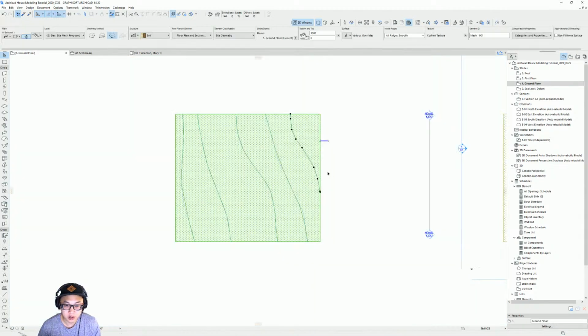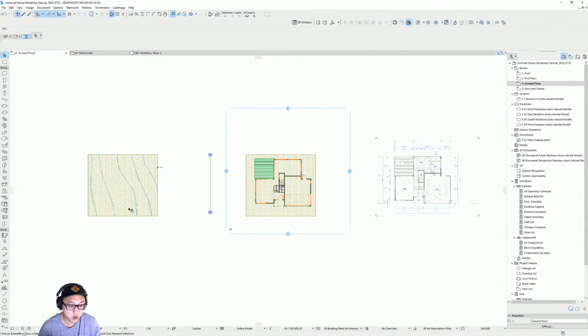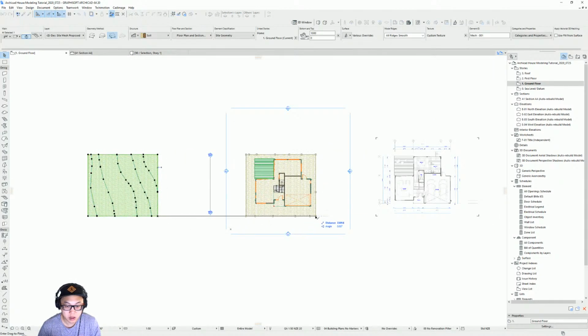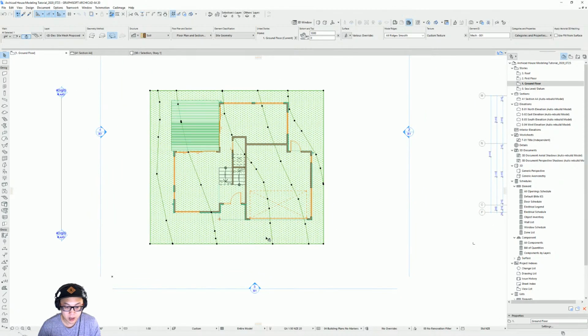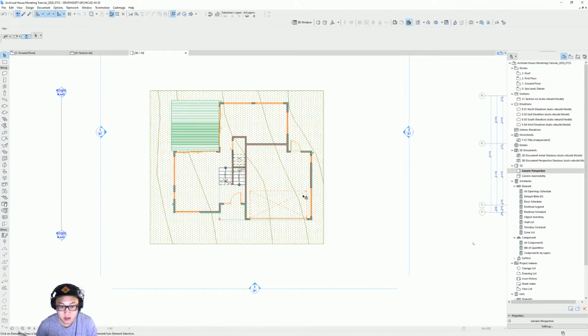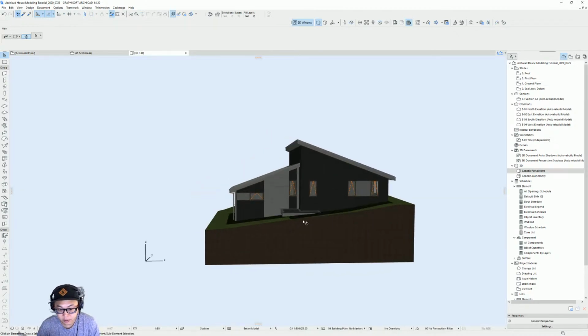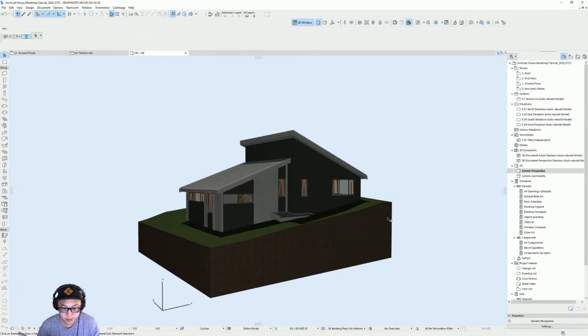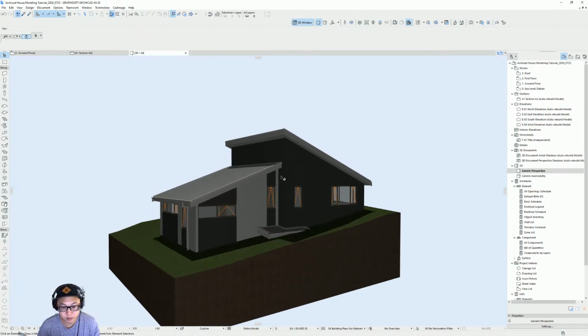And what we can do is to kind of place it where it was before. Just gonna mouse over there, click. And if I know there's, in this case, two elements on top of each other, a technique to select an element that overlaps is by pressing shift, pressing tab, click. So this one is the mesh that doesn't have the lines on it, and then delete. So now I got my mesh in my house. But you can see I would need to move the house.